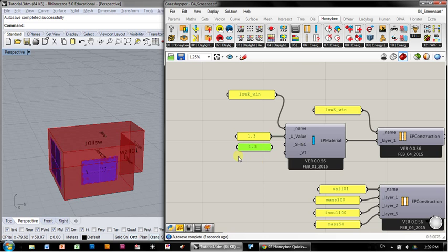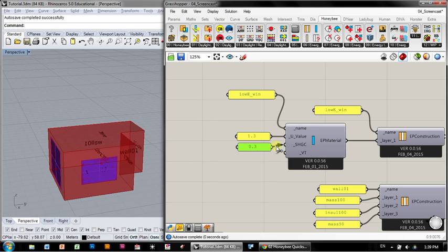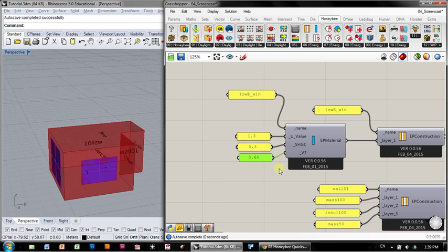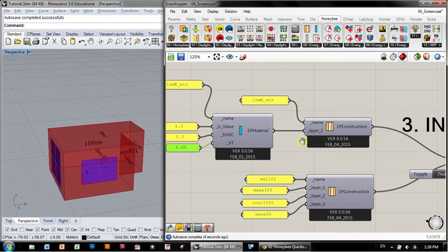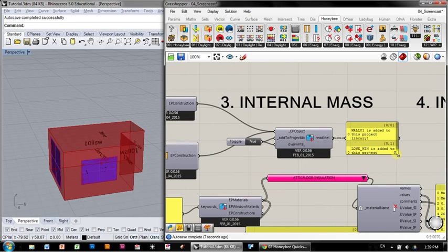And then a solar heat gain coefficient of maybe 0.3 and a visible transmittance. Let's do like a Loisos 3 coating would be, say, 0.64. So that's my material, and I think in this case it all added to the library just fine.